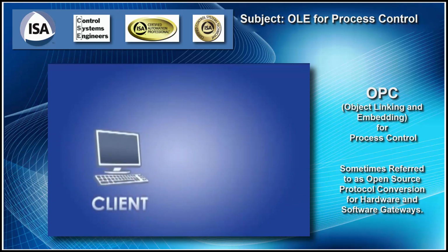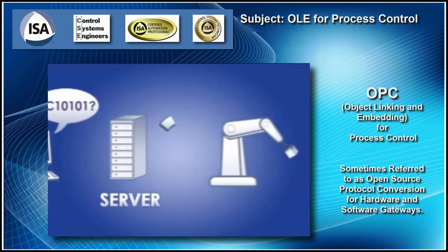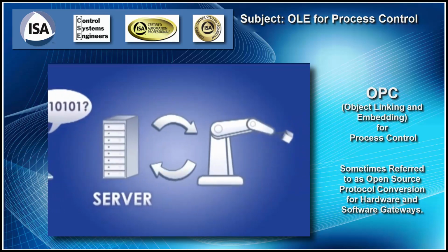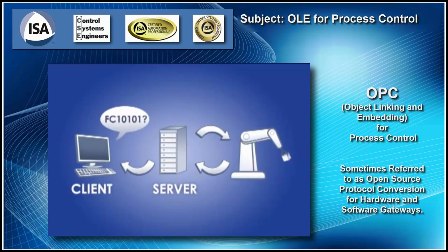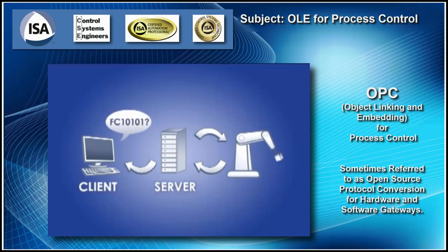Similarly, an OPC client makes a request from an OPC server. Let's say, what's the value of FC10101? The server then polls the device for the value and delivers it to the client. It sounds simple, but it took some great minds to simplify what was once a complex and costly data access problem.